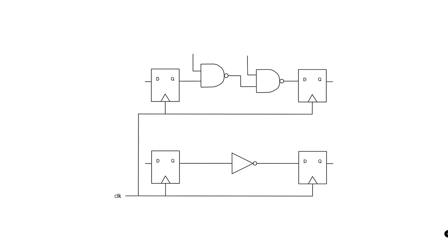The clock is a special signal in the sequential machine, and we place strict requirements on how it behaves. In a basic sequential machine, all the registers are controlled by the same clock. The worst case delay for all the logic in the machine limits its clock period. We expect operations in the sequential machine to happen synchronously. This means that the clock signal should arrive at all the registers within tight tolerances.